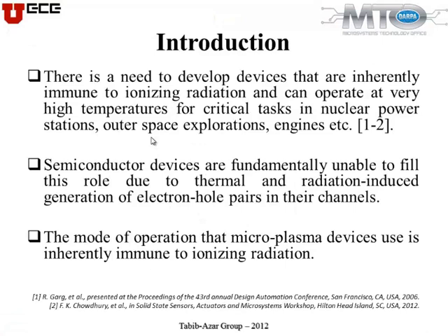So, microplasma field effect transistors. There are lots of devices based on plasma, and these are gaseous plasmas. You have basically two electrodes, and you apply a voltage, and you ionize the gas between the two electrodes. And of course, light comes out when you ionize the gas. We have added a third electrode to control the amount of plasma that we generate between those two electrodes.